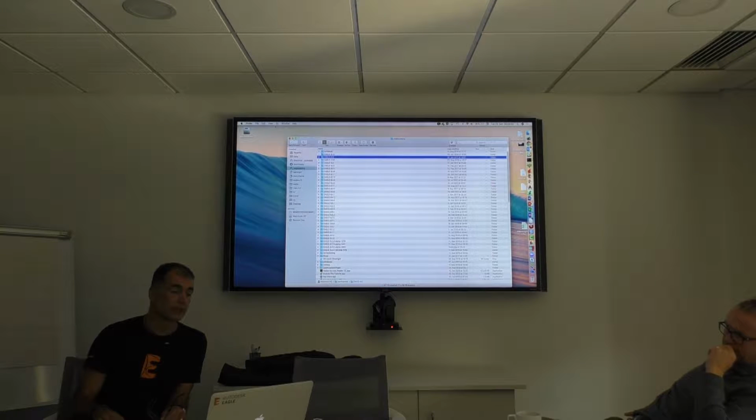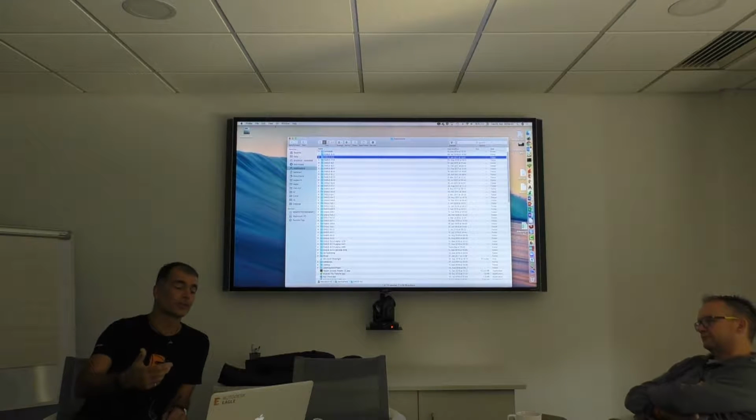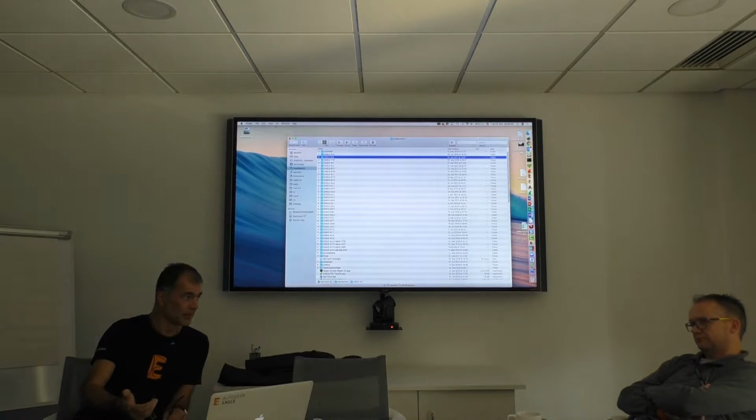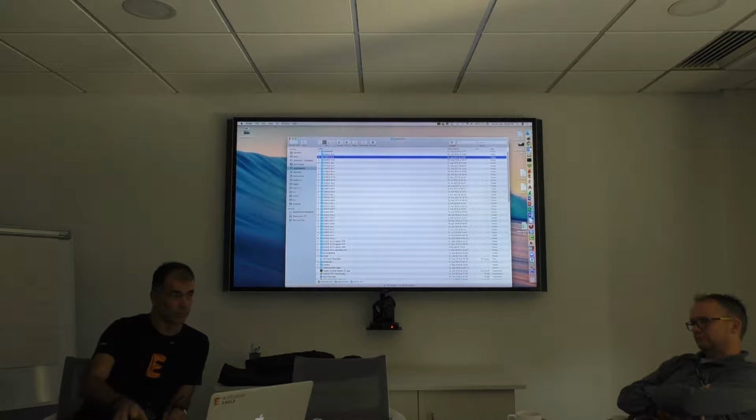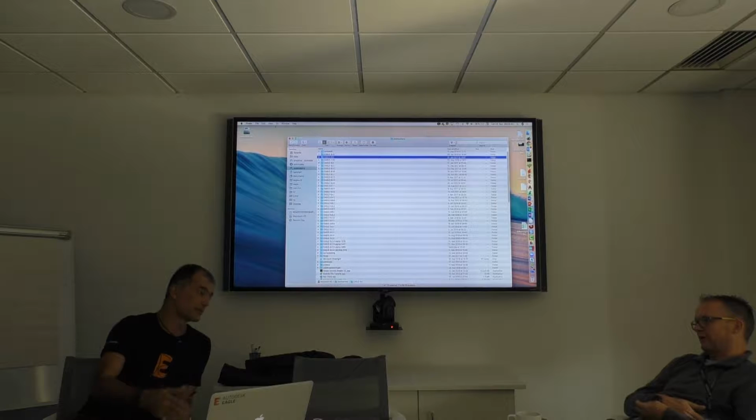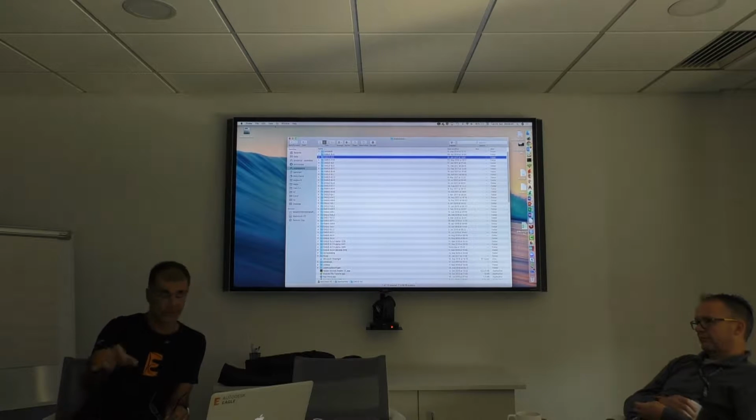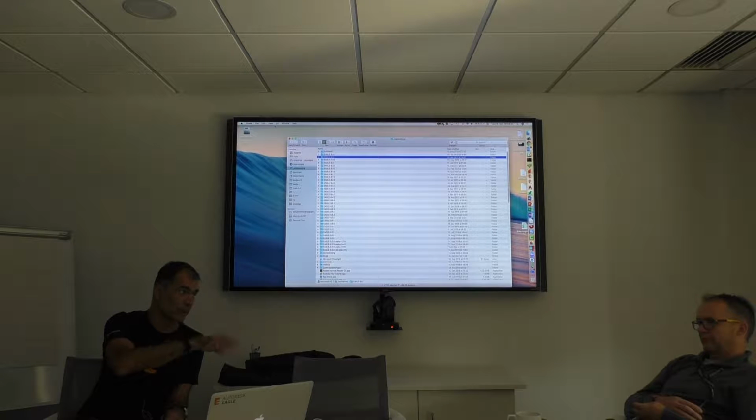And if you want to edit one of the files that come with Eagle, they're all read-only at the moment. So if you want to change it and save it, it tells you you have to save it with another name, in another folder, and that's typically in My Documents, Eagle, and then we have the subfolders where your projects will be. That's also true for user language programs, libraries, and all that stuff. Okay, good.